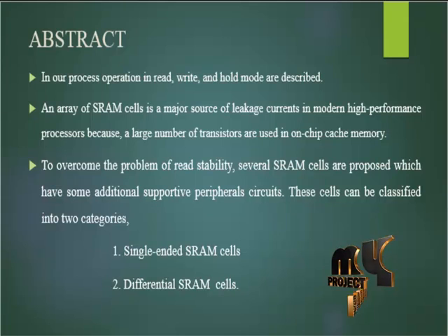In the proposed differential structure we have designed, the sense margin is improved, so we are using the differential structure. We also show larger read current, shorter read delay and better read stability. The low power 8T cell is robust to process parameter and voltage variations. Our proposed 8T SRAM cell also has a higher read current to leakage current ratio, and the leakage current and power consumption are also less.